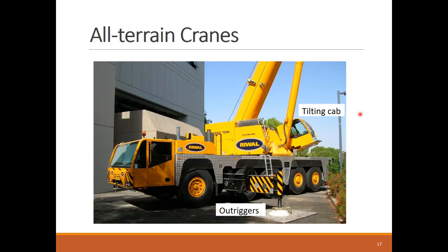All-terrain cranes come with a high price tag compared to truck cranes due to their combined benefits of mobility on and off roads. They are best used in job sites with multiple lifting locations with no need for graded sites. They are also capable of pick and lift operations where they can lift a load and move with it in the air for a short distance. The only other crane capable of this pick and lift operation is a crawler crane.